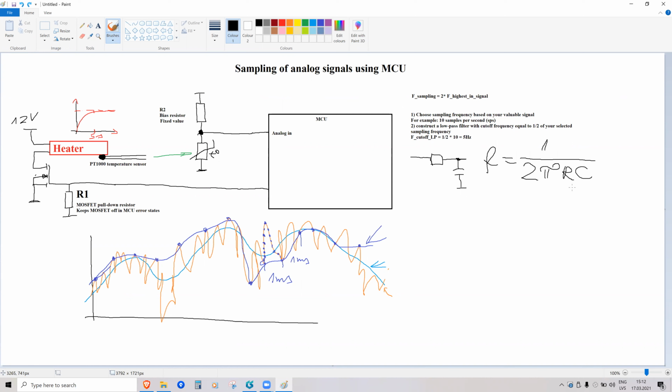And the second thing is, in this circuit, you already have a resistor here. Let's say I put a capacitor here. To charge this capacitor, the current has to come from the left side, because the input doesn't give or take current. It is an input with high impedance.